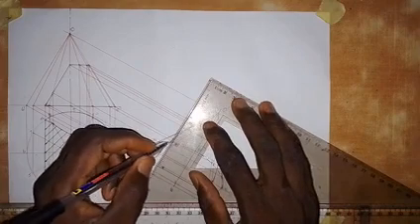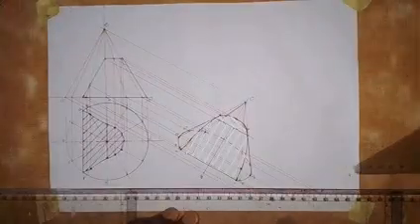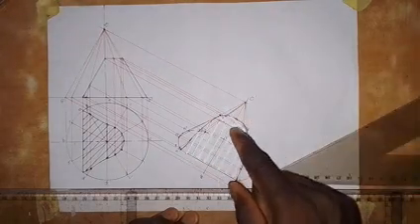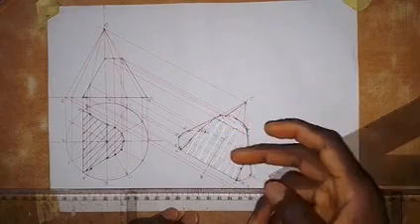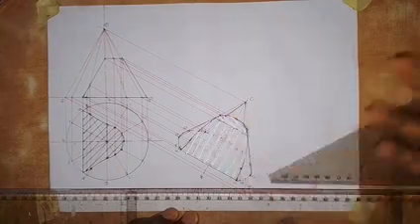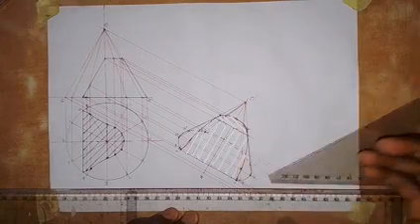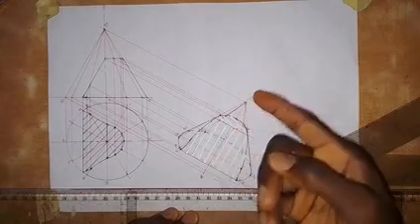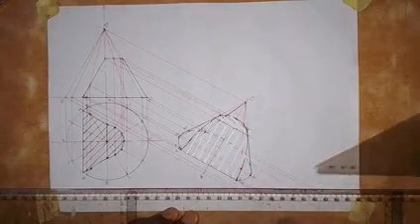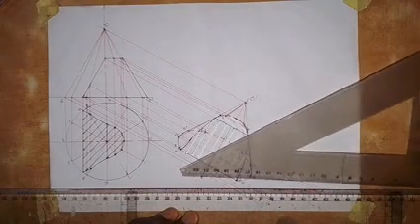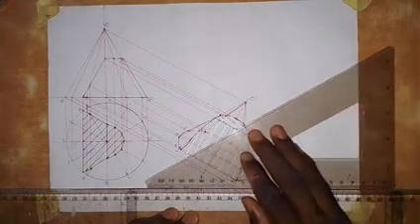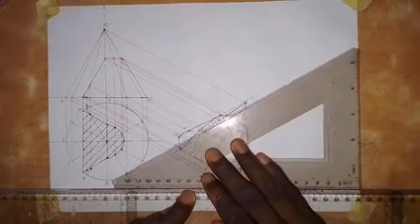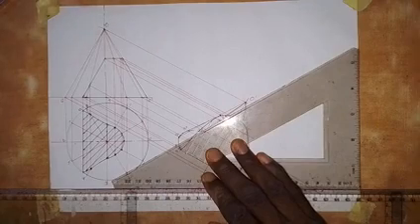I will use the 60-degree set square to do this. Let's produce arching lines on this surface. We produce them separately because we have two parts here. The arching lines that I produced before were not okay, because the lines were parallel to this line that we drew with 60 degrees. That's why I cleaned it and I'm going to produce it right now. So I'm using my 30-degree set square to do that. I would have used 45, but I can use 30 for this.